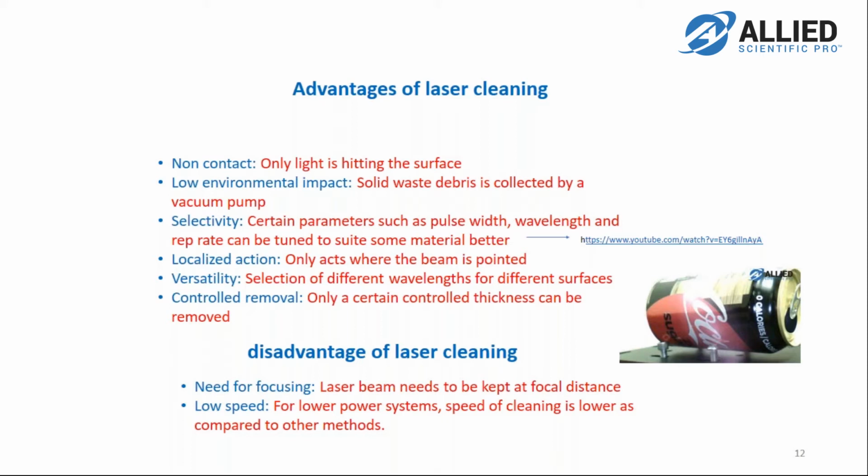And I will show you a video of this Coke Zero can that has certain colors: black, red, and white. The video will show that laser cleaning only removes the black, although it's shining on other colors. So that's a big advantage.